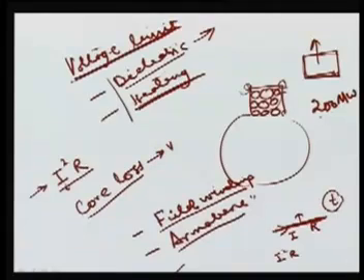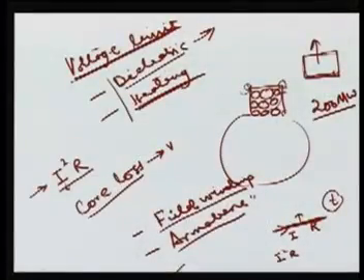That is why for high rating power generators, where there will be more loss, we go for better and better cooling, that is, hydrogen cooling or water cooling. Various types of cooling schemes exist, and the performance depends on that. If your generator is rated at 200 megawatt and the hydrogen pressure is reduced, then you cannot operate the generator at 200 megawatt. Why? Because the loss occurring is not taken out from the air gap of the alternator.